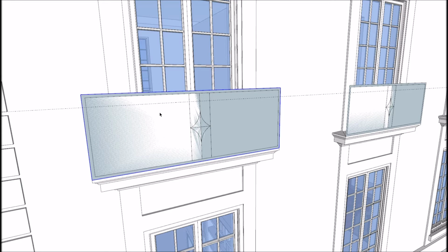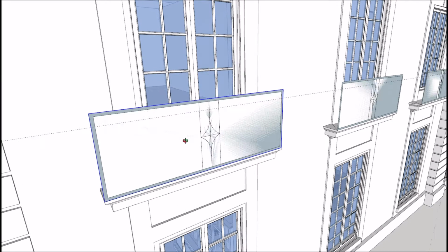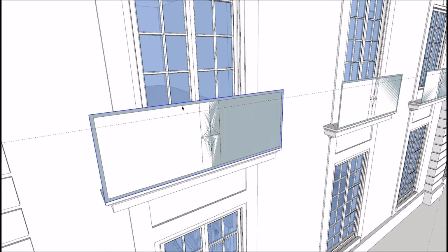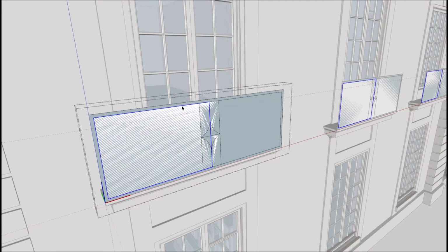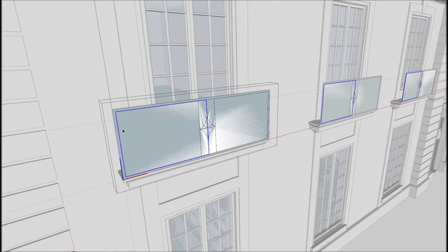I simply drew the rectangle, right-clicked, and chose Make Component. And then I went inside that component and I made the second component inside of it, which is 1/2 of the balcony. And as I develop that half of the component, as we saw, the other half will change accordingly. I just want to mention one other useful trick here, and that is that I can make